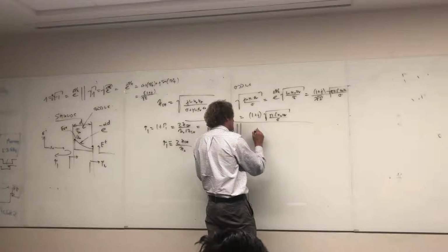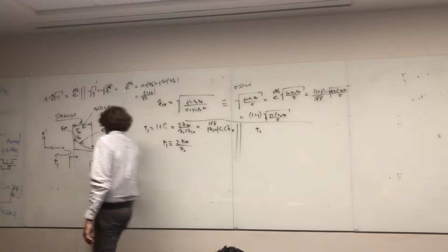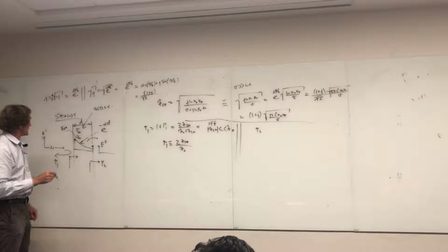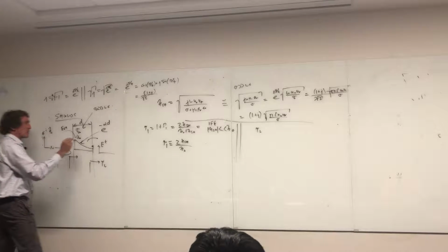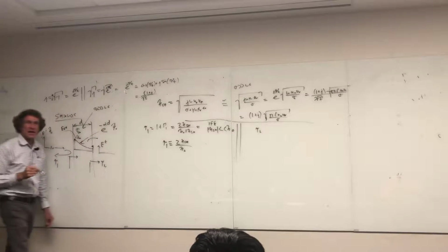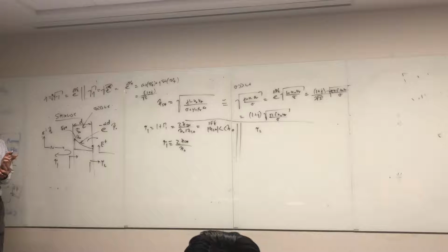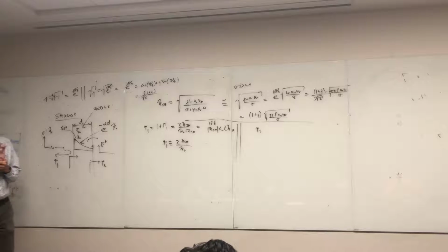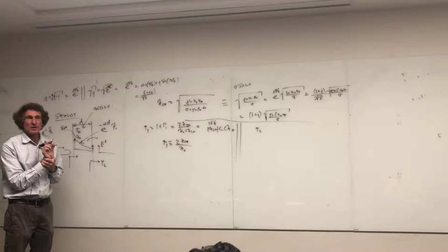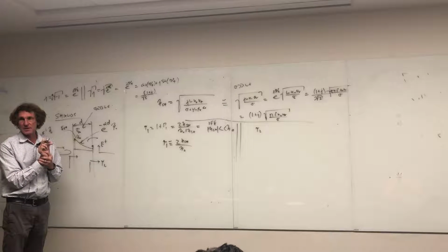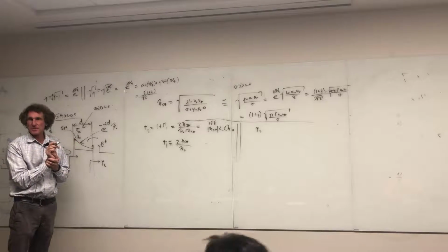We need tau 2. Well, tau 2 is going to be the transmission coefficient going from the shield out to free space again. And by the way, I know there are complicated problems you can create, but almost all shields have air on both sides. Almost all the shielding problems you run into assume air on one side, air on the other. Very rarely do you have to worry about something else. And we don't generally get into multi-layer shields. Even though that's addressed by some people, you don't need that level of complexity. You just get the metal thick enough and it stops everything.